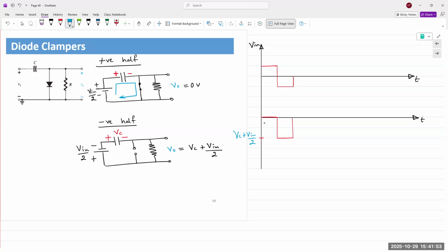If we reduced the frequency a whole lot and slowed down the positive and negative half cycle, and if the capacitor was a really large size, then we would observe that slope, which we actually did in the pre-lab as well as in the lab when we put in an output load resistor that was far smaller. It discharged faster, so the slope was more pronounced when it's trying to discharge.